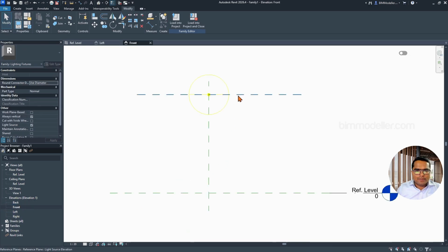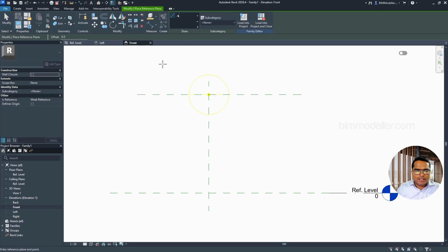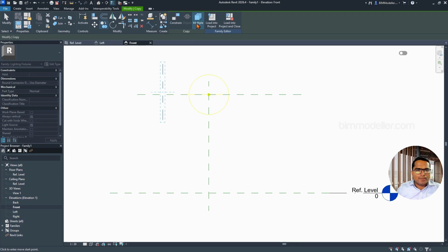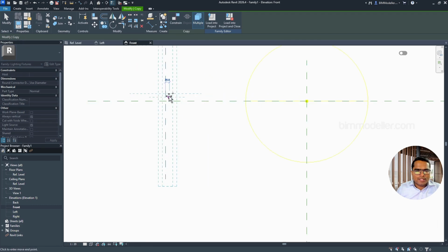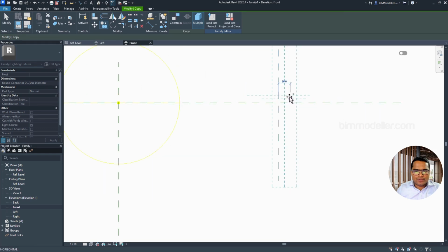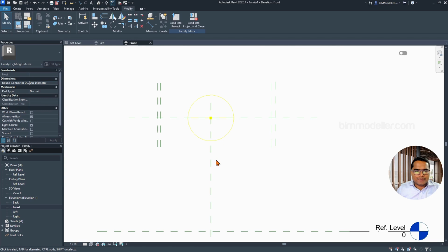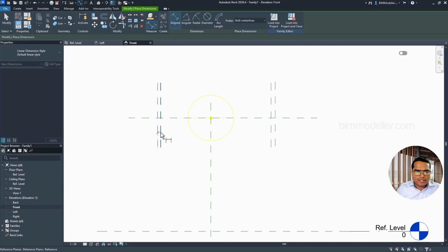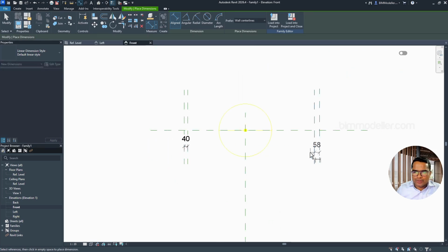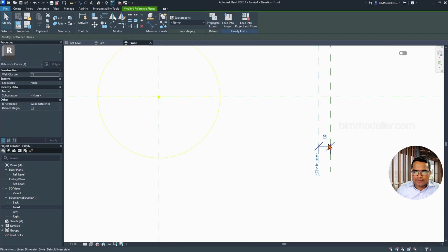I can create my constraints on the length side. This is going to be the left side. We can do it here, and we can make a copy, and it's going to be a multiple copy. One is here. On the other side, we can have two more like this. I'd like to have a thickness here. It's going to be a few millimeters, say 5 millimeter.